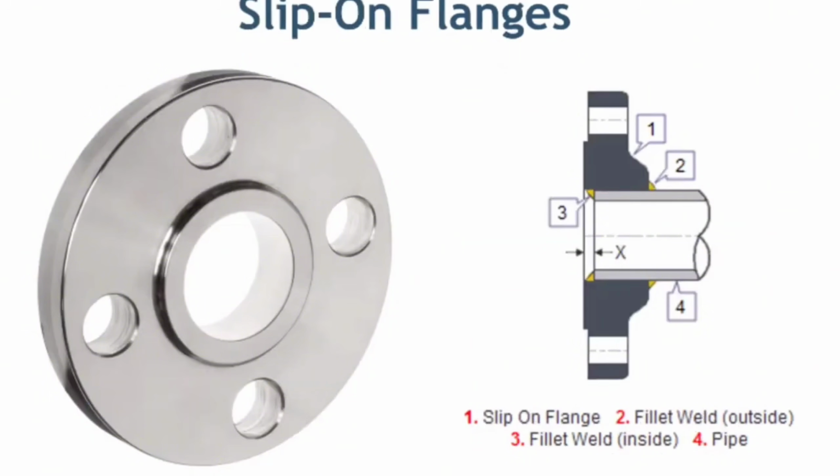The next type of flange is a slip-on flange. Slip-on flange, as the meaning of name, is a flange slipping on the pipe or fitting when connecting. Slip-on flange is essentially a ring that is placed over the pipe end, with the flange face extending from the end of the pipe by enough distance to apply a weld bead on the inside diameter. Slip-on flange is connected to the pipe by two welds, one on the back side of the flange and one on the inside of the flange.